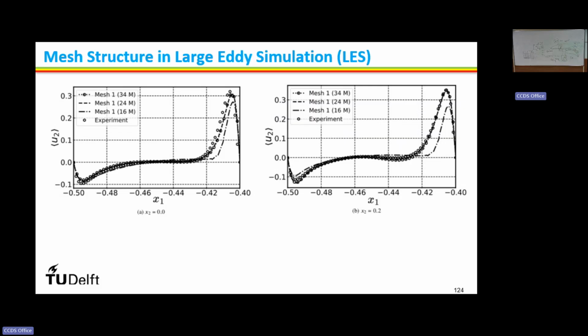So this much intensive calculation, the computational requirement is more, right? That's why LES is still not a usual thing for industrial practice. For simple geometry, yes: flow across a cylinder, natural flow in a cavity, those things we can do. But imagine an industrial pump, blower, turbine. How much computational requirement will there be, right? So this is the thing.